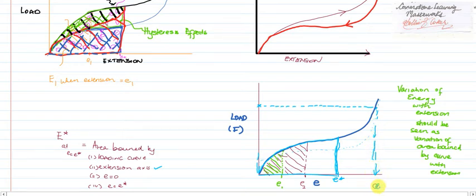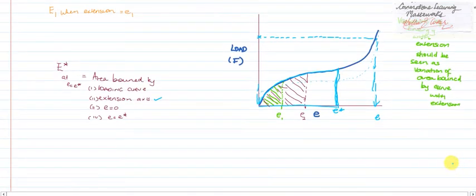Once you get the subsequent extension, you can find the kinetic energy by finding the area under this graph up to this point. So you call it energy, well, E star. Okay? So for the next part, we have the plan design. You're going to use theory and say E star, which is the energy stored in the rubber band, will all be converted to the initial kinetic energy of the bullet.